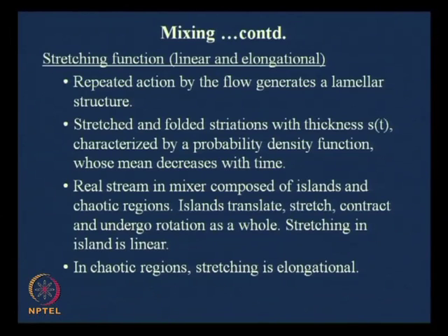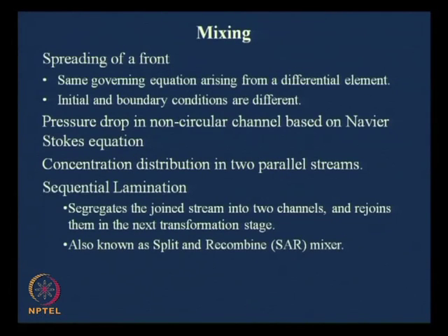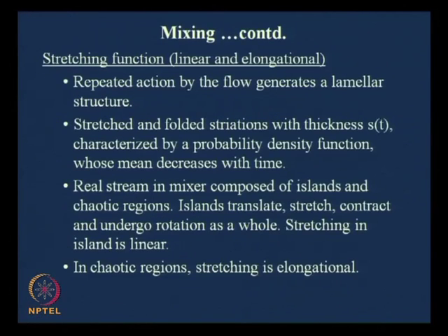That is what I would like to point out, and I think by now I should have made my point clear. Now, if I see what I have in the slides, we were talking about sequential lamination, which segregates the joint stream into 2 channels and rejoins them in the next transformation stage, also known as the split and recombine mixer. Then we said there are two types of stretching functions. One is linear, another is elongational.